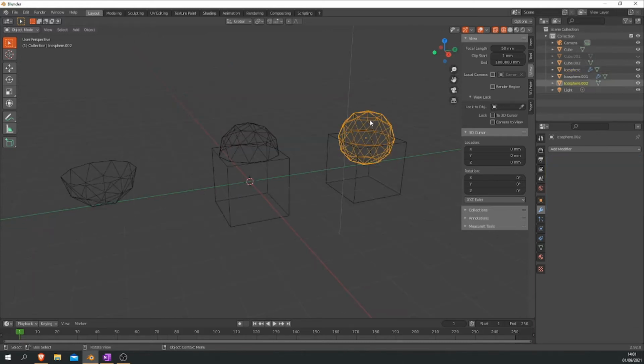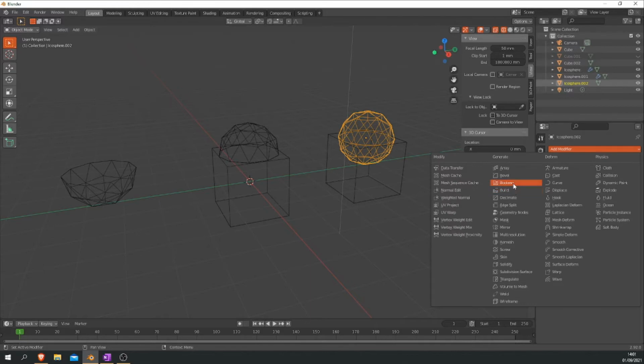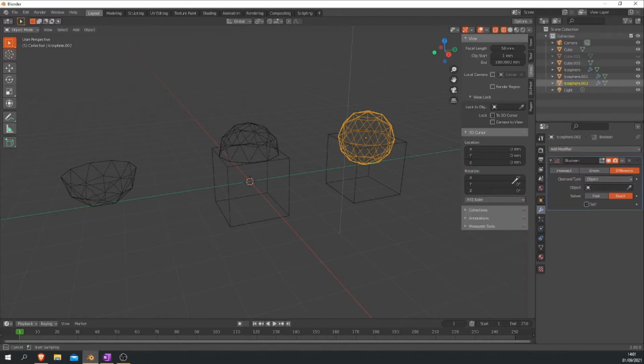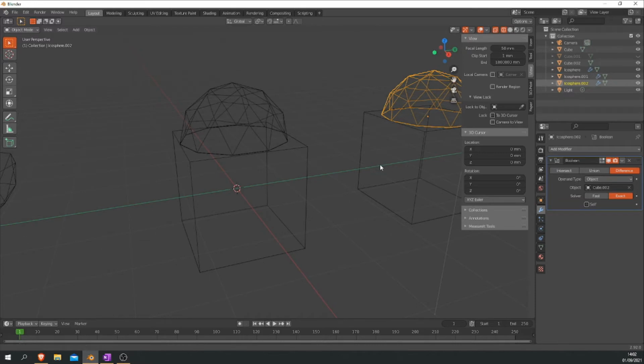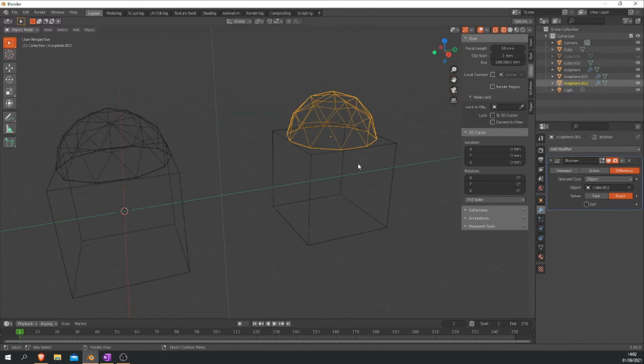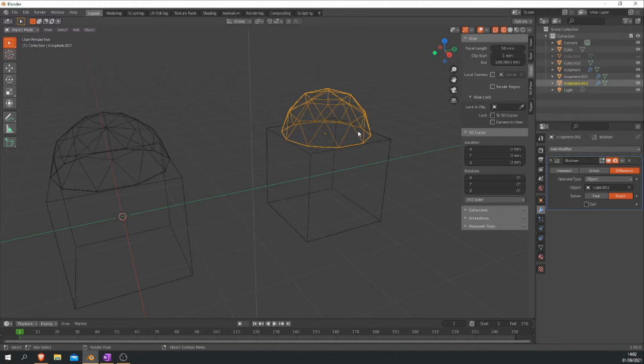And lastly, we're going to use it again. This time we're going to choose difference. So again, choose the eyedropper, I'll just go back into normal mode, cube. And what this is, is kind of the opposite to intersect, where if we go to that now, it has basically removed everything on the inside, but they're not joined. They're still two separate parts. It's just modeled the difference between the two objects, so it's taken that away.